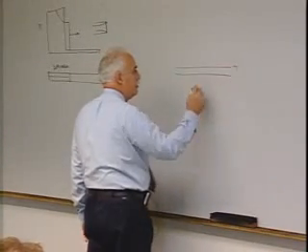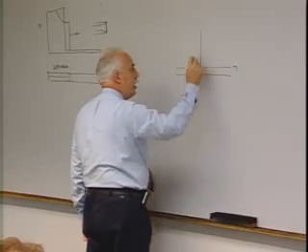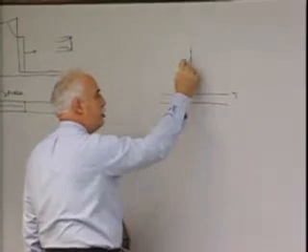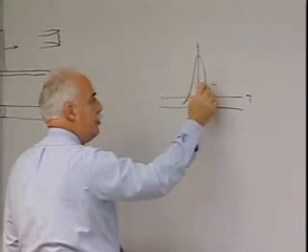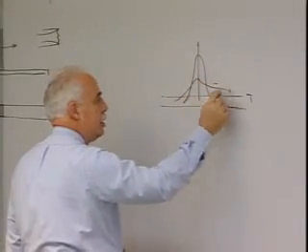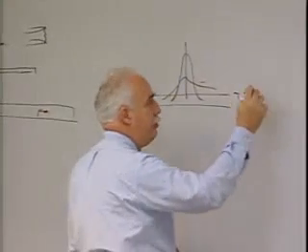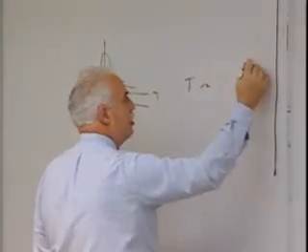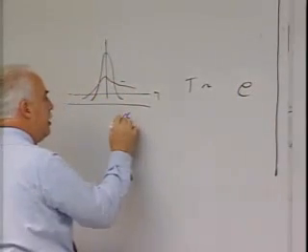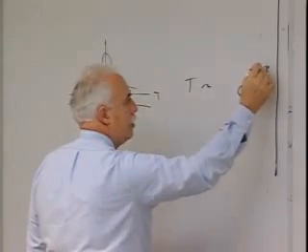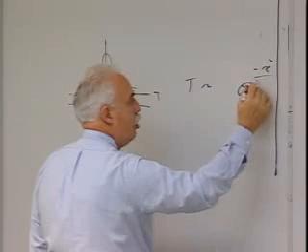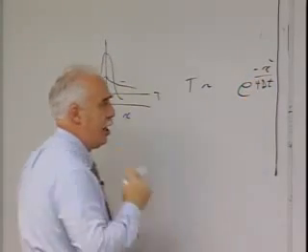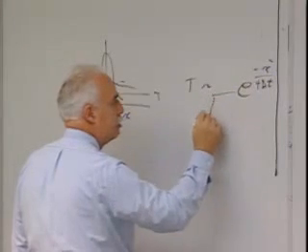temperature initially, and you have a heat input. You end up with a distribution of temperature which diffuses out. Okay, functional form of that, if you recall, T is proportional to an exponential, let's call this x squared over 4 thermal diffusivity times time, and there's a square root.